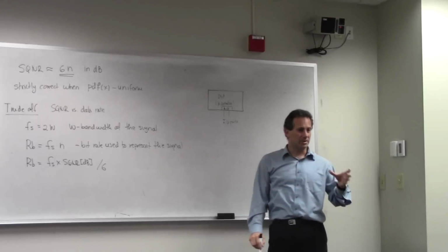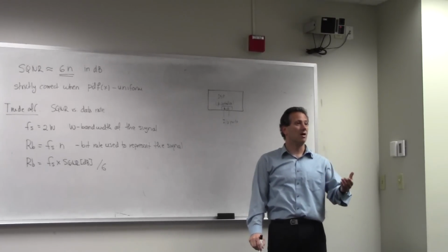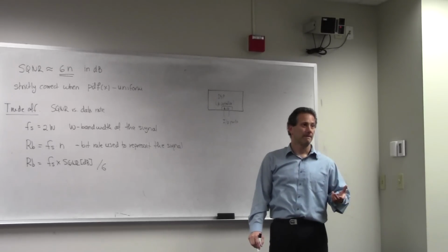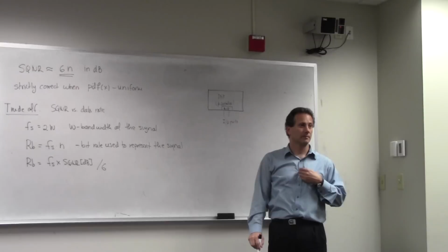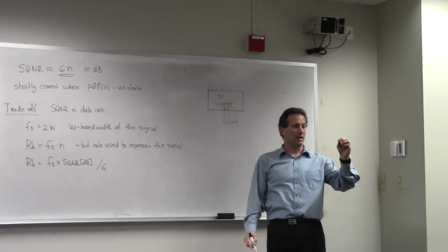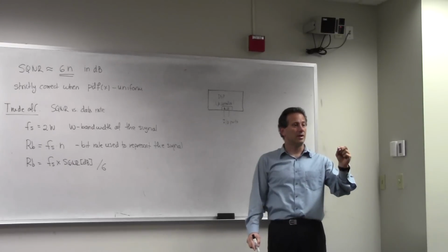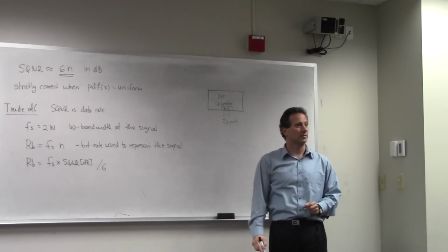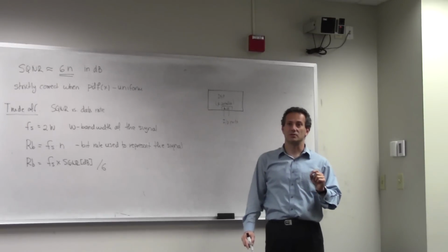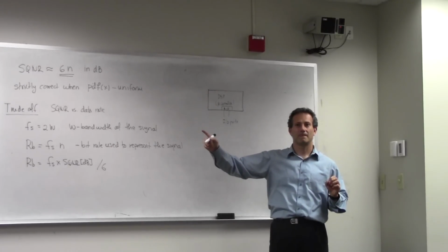And what comes with the data sheet associated with a particular microcontroller or DSP is how many bits your quantizer has. It says in the data sheet, this one comes with an I/O port that has a 10-bit quantizer, right? And the range of levels 0 to 5 volts. Uniform distribution. But you cannot manipulate that. No, uniform distribution is not a problem of the quantizer. But they won't say if it's a non-uniform quantizer?